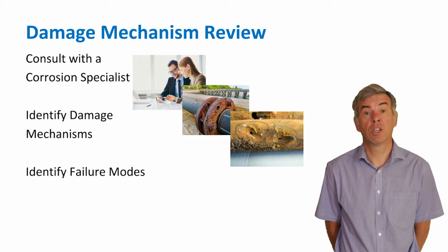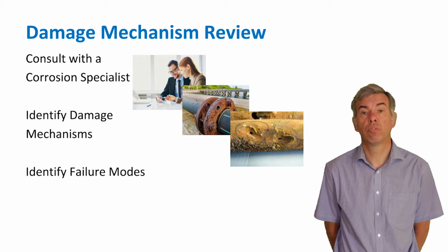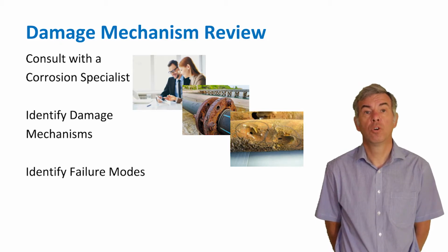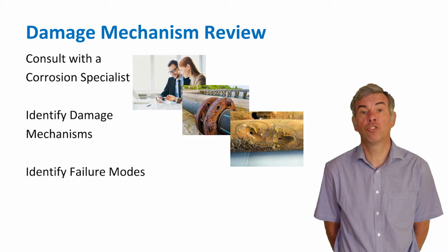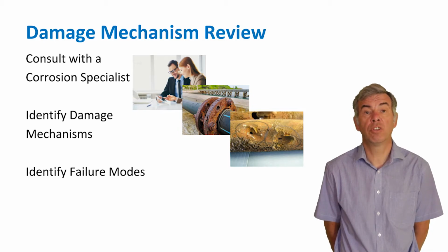Failure modes are kind of what they say, really. They define how the component will fail. Will it rupture? Will it show leakage or fracture? All of the assumptions about design pressure, temperature and materials should be noted. And all the process conditions, including startups, abnormal conditions and things like that, should also be considered.